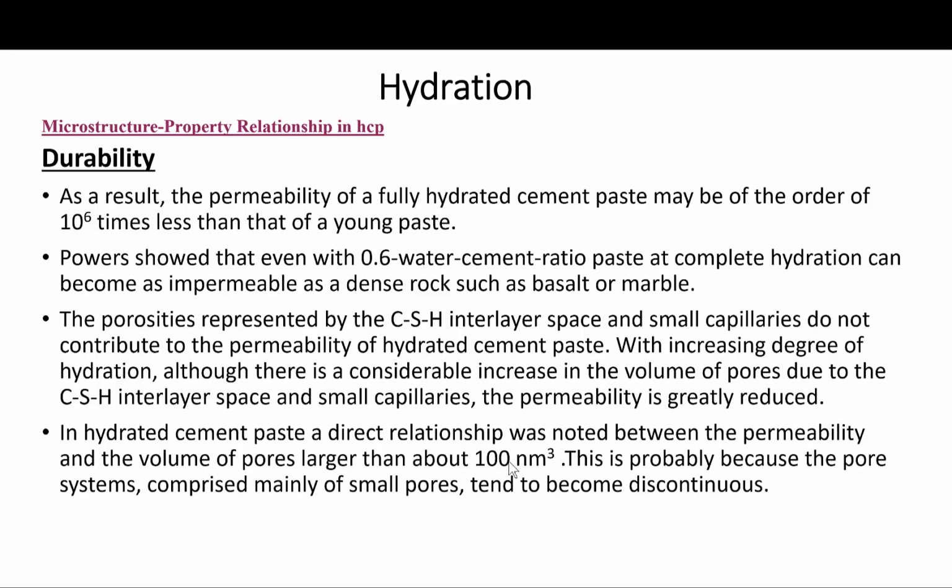Also note that the porosities represented by the calcium silicate hydrate interlayer space and small capillaries do not contribute to the permeability of hydrated cement paste. On the contrary, with increasing degree of hydration, although there is a considerable increase in the volume of pores due to the calcium silicate hydrate interlayer space and small capillaries, the permeability is greatly reduced.